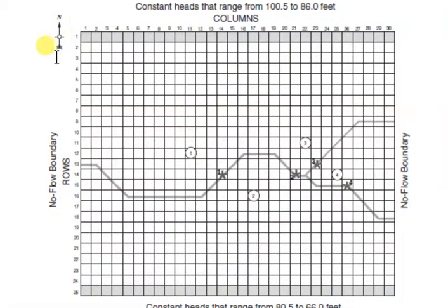One of the interesting elements of this problem is the way the pumping is allocated to the 4 wells. Well number 1 withdraws at the same rate, that rate to be determined by GWM, but it will be the same rate in all 12 stress periods. Well 2 has seasonal withdrawal rates. In other words, it will be able to pump at a different rate in winter stress periods, at a different rate in spring stress periods, and so on.